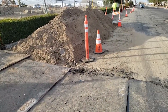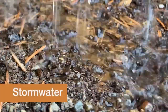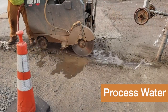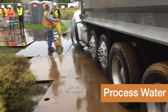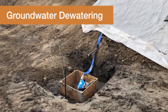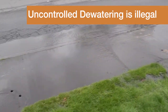There are several types of water that we're going to encounter on our projects, whether it's water that falls out of the sky, which we call stormwater. We may be pushing water through a machine to do work like a pressure washer or a saw cutting, and we call that process water. Or water can actually come up through the ground, get into our hole, and we need to pump that water out of the hole and into the storm water. We call that groundwater, which we now have to dewater into the storm system without creating risk to the storm system. So all of these different water classifications require a different management system.